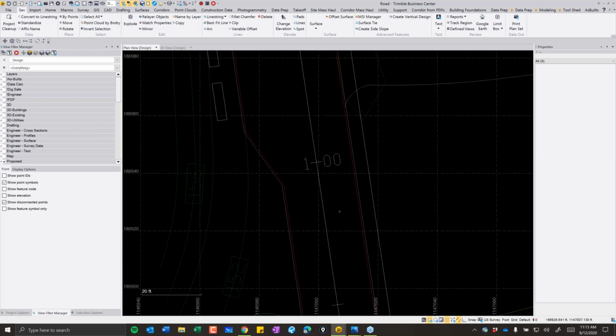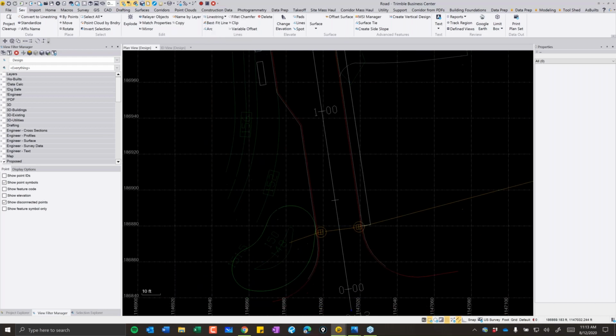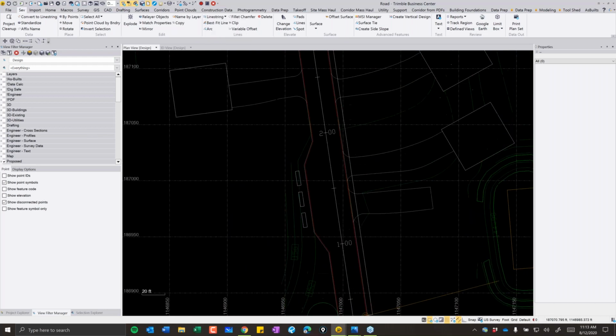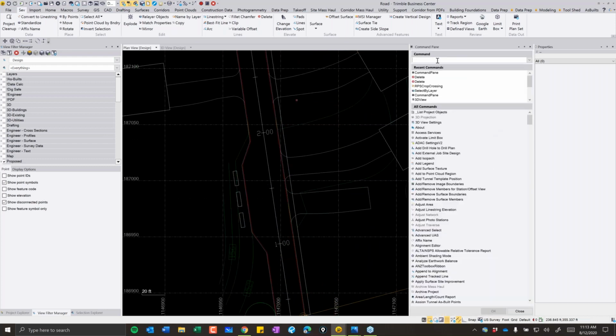Yeah, a lot of people do the trimming back of the contours around the curb and gutter and flow section, especially around islands in parking lots and stuff like that, because you're going to blow through the islands probably anyway. Exactly, yeah, you're right. Yep. So now that we have that, I'm going to go into the vertical design.